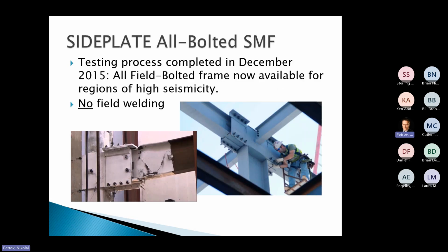All bolted connections. The first connections that they had that hit the street were the not all welded, but connections that required field welds. But they were working hard to get the bolted connections online. And once they did, I think that since they had those approved at the same level as the welded ones, we have only seen them use the bolted connections. I mean, it's a no-brainer. There's more angle and material and stuff associated with the bolted connections, but you're obviously going to save costs if you have bolted field connections instead of welded field connections.